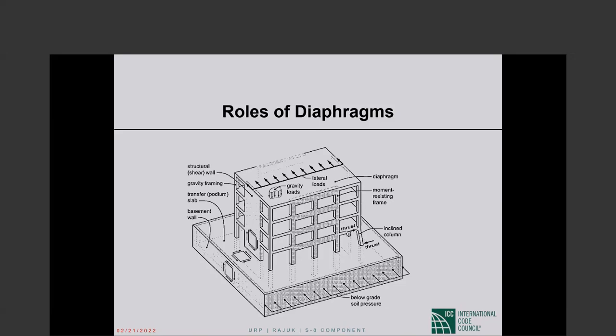let me pause there. So the dead loads and the live loads are gravity loads that cause out of plane bending of the slab, and a slab has to be designed for that out of plane bending. We have to put reinforcement in to carry the out of plane bending and the accompanying shear.